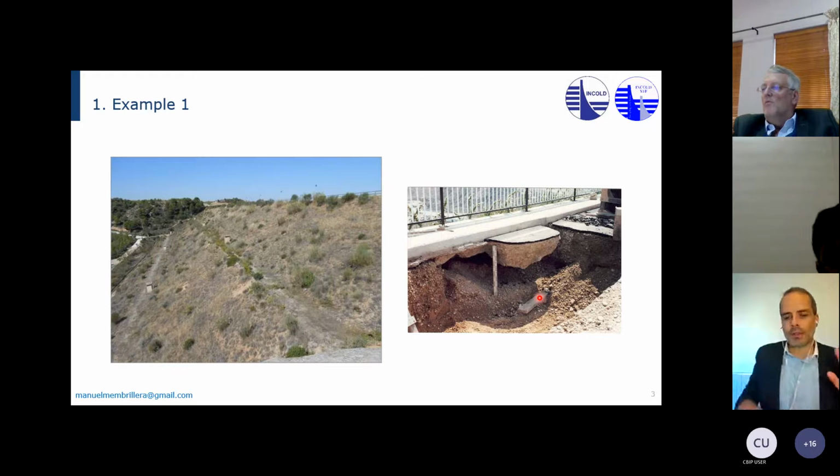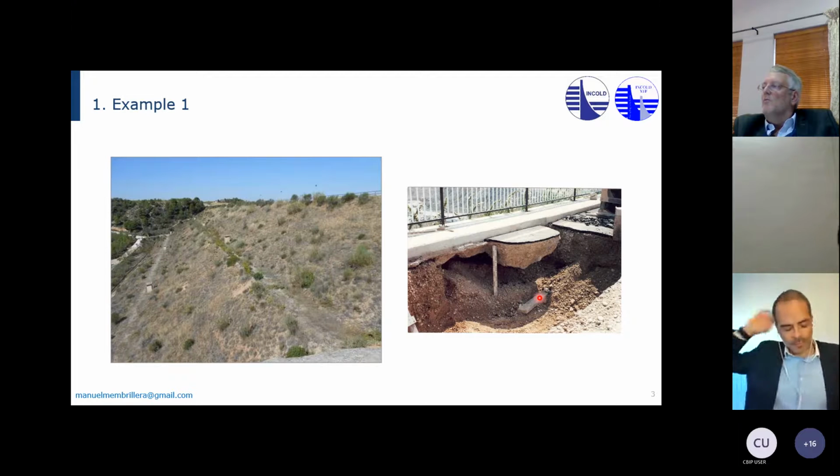So they were losing water in the reservoir with this old mine that was connecting the valley of the reservoir with another valley. And so they had to grout that and make a concrete plug, and they installed piezometers and manometers that we're still monitoring today. So that's in the reservoir.